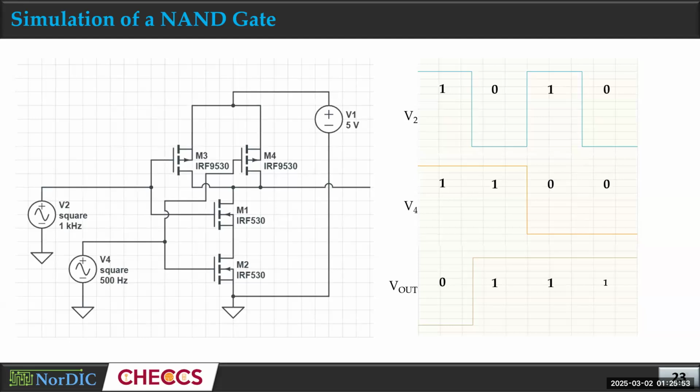So you should put one PMOS here, one NMOS here, and similar thing here, so that you can just connect the gate. That will make your source and drain connections difficult, but you can do that later. Just try to align one PMOS, one NMOS, like the inverter, like two sets of inverters.